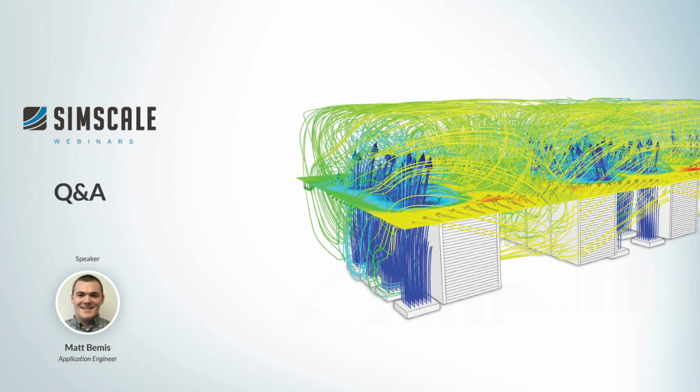So you can define, we call it a fan boundary condition, and this will allow you to upload a CSV file defining flow rate versus static pressure. You can certainly do that. I encourage you to check it out. I've been using it, and it's a great feature to have.